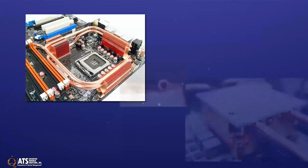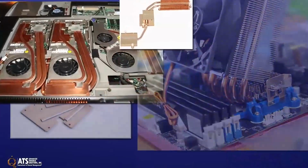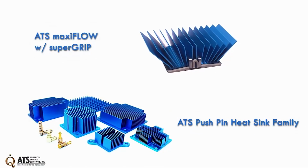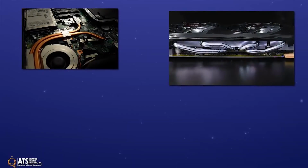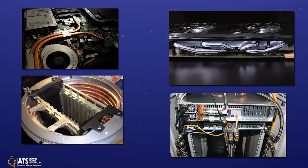Heat pipes come in various shapes and sizes, though the most common are either round or flat heat pipes. Heat pipes can be bent as required for both system and thermal requirements. Round heat pipes are generally used for transferring heat energy from one point to another. Flat heat pipes, also known as vapor chambers, work conceptually the same as round heat pipes, but their shape allows for different applications. Applications can include embedded heat pipes and heat sinks, such as ATS's MaxiFlow heatsink family or ATS's pushpin heatsink family, laptop computers, embedded heat pipes for single-board computers, military applications, RF, telecommunications applications, and server cloud computing.